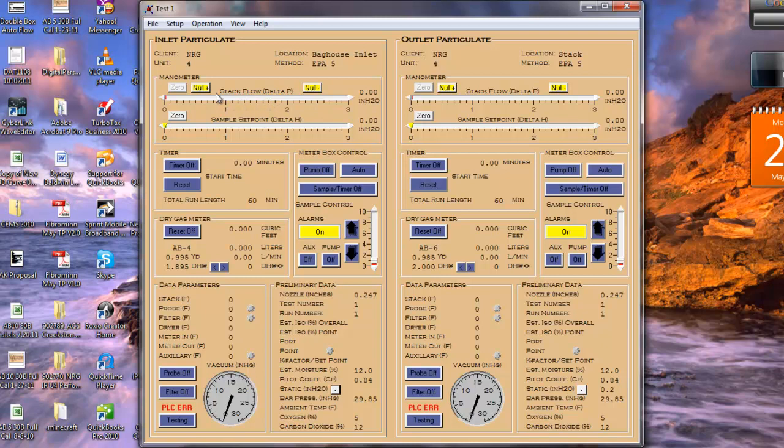You can use these two buttons to enter them both, and that opens up a three-way valve which allows the pitots to be zeroed, and if they're not zero, then you can press the 0 button to re-zero the manometer, and then shut this off, and you can see the 0 becomes disabled.